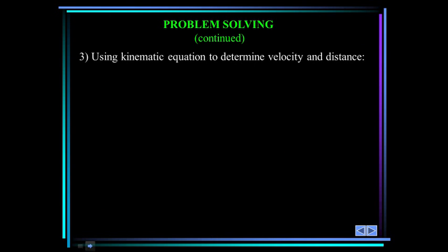Now we have acceleration as a function of time, so we can use the kinematic equations from chapter 12 to determine the velocity and the distance. So let's write down a again. a is equal to 8t squared minus 4.616 meters per second squared. Now remember that the velocity is the initial velocity plus the integral of a dt. The initial velocity was given as 2 meters per second.